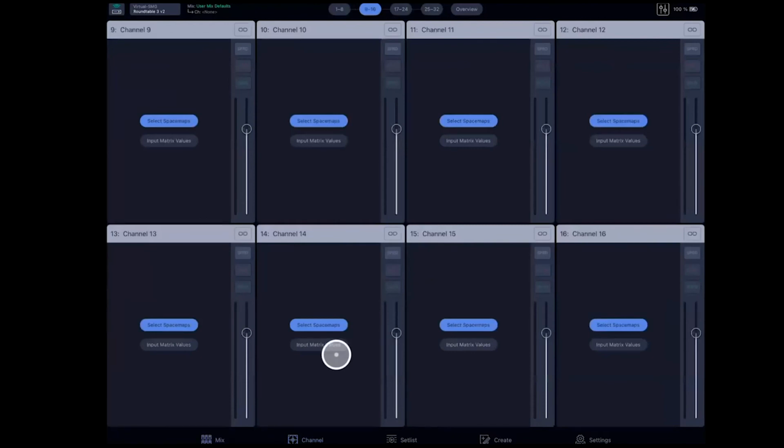So this idea, it's all about you as the mix engineer. And we've tried to create a tool that allows you to work with the tools that you have and work with the outputs and the speakers that you have. We're not saying you need 5 speakers in front. We're not saying you need 12 speakers in back. What we're saying is take your inventory and think about the fundamentals of systems design. Pick the right speaker, put it in the right place. As we've seen, if you put it in the right place, you can really get most of the coverage area for surround done right, and then point it in the right direction.